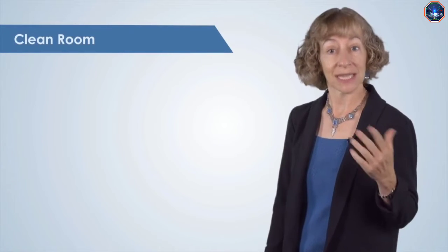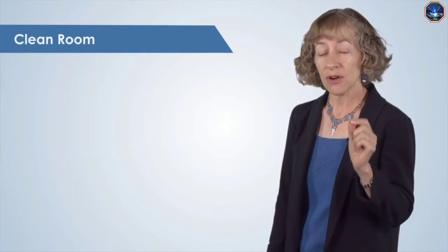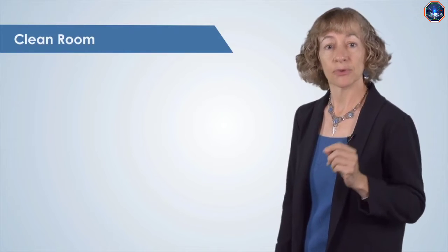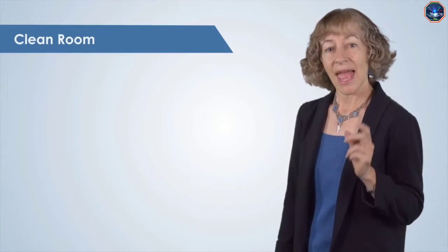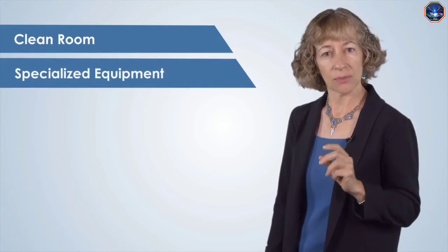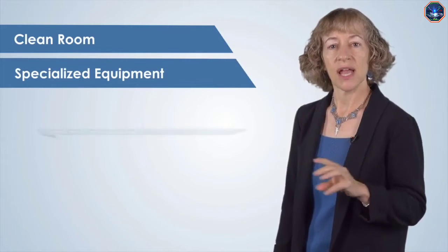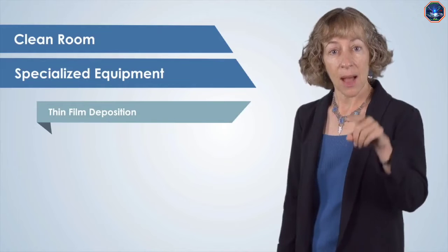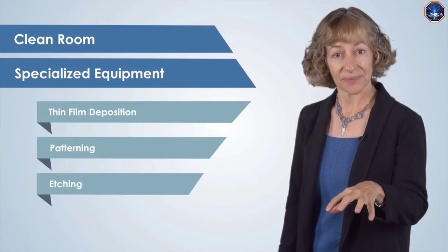The basic components needed for nanofabrication are, number 1, an extremely clean environment called a clean room, in which there are very few particles. That's where we perform the fabrication work. And number 2, specialized equipment for 3 basic functions: thin film material deposition, patterning, and etching.